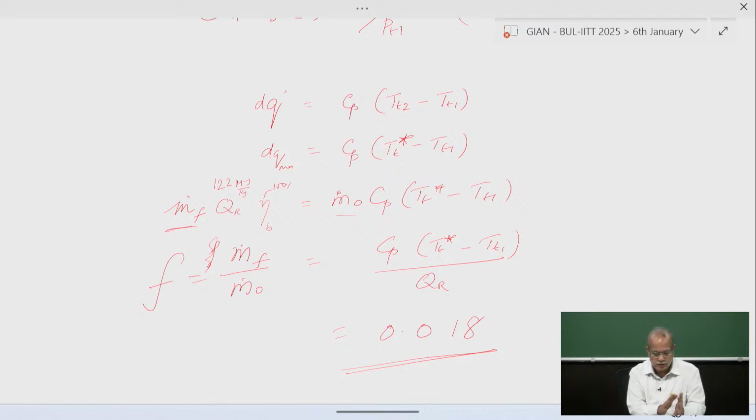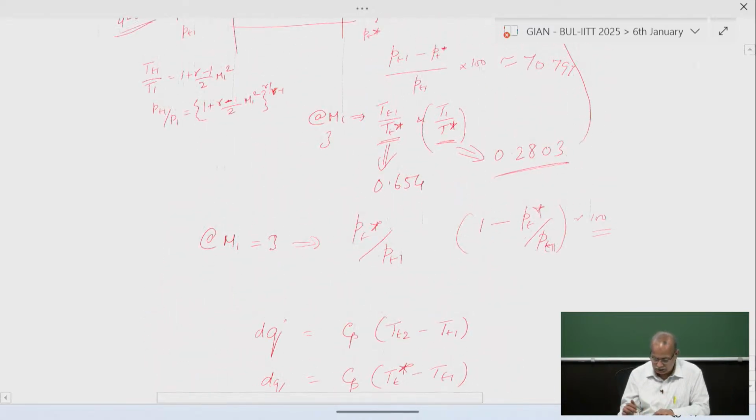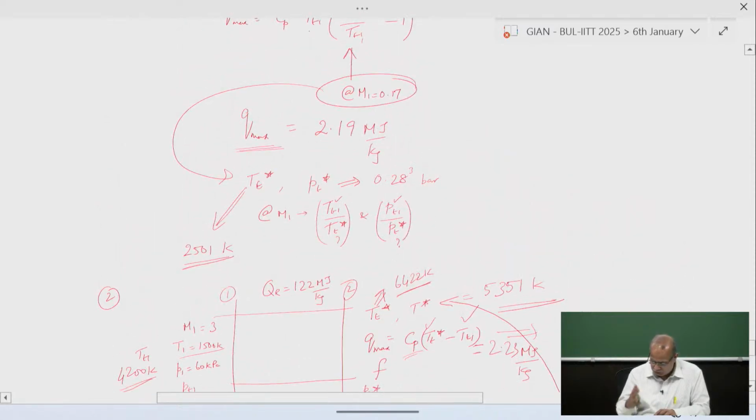And in the afternoon class we looked at the combustion process through the Rayleigh theory, where we demonstrated that we can use the Rayleigh theory and Rayleigh tables to calculate the combustion parameters. So you can calculate the fuel-air ratio, the pressure, temperature, the Mach number, and how all these things change in either a subsonic ramjet or a supersonic combustor.